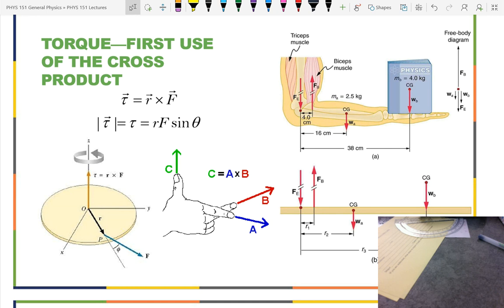Now on this note, if you are putting in a screw, a lot of people have memorized just a little four-word mnemonic to determine which way they need to turn that screw. What's that four-word mnemonic? Righty-tighty, lefty-loosey. That comes from the right-hand rule. Because the screws we use, we call them right-hand threads. Right-hand threads mean that they obey the right-hand rule. If you rotate it this way, it's going to go that way. If you rotate it this way, it's going to go that way. So our threads are called right-hand threads.